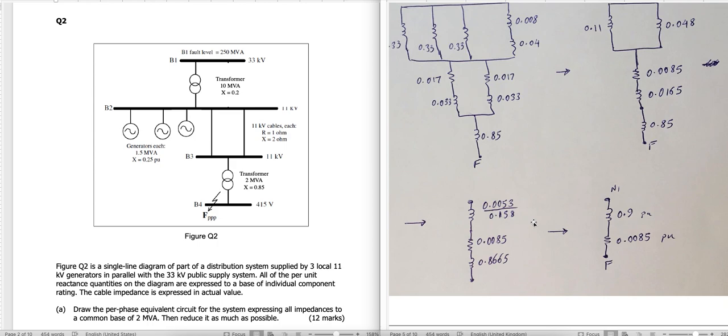Yeah, but you can't add them because this is actually 0.9j, not 0.9. For simplicity, you didn't put j, but this is 0.9j. Because this is in complex numbers, this is the imaginary part, and this is the real part. Together they form impedance. The impedance is R plus jX. This is a complex number, you can't add them algebraically. They're like two vectors with a 90 degree phase difference.